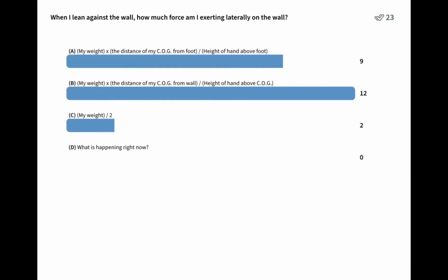Here's my foot down here. Of course, the vertical force on my foot is my weight. I'm not going to use numbers because I don't need to embarrass myself here. But let's just pretend my center of gravity is somewhere here. You could idealize this more or less as well. I've got a pin here because there's some horizontal reaction and some vertical reaction helping to provide support. I can think of this hand as a roller maybe.